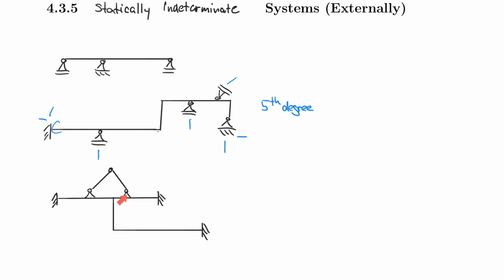So what I'm trying to tell you here is that this is your hinged, simply supported frame that is statically determinate, and it just sits on top of the structure. So this is just adding forces to the system. So this is not counted in my statically indeterminacy, but I have 1, 2, 3, 1, 2, 3, 6, 1, 2, 3, 9. And so this is to the 6th degree, right?